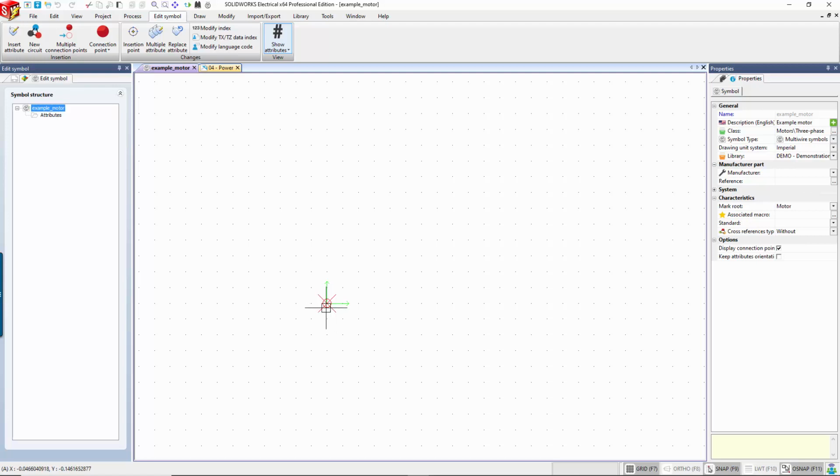The insertion point means that when you drop the symbol on the page, where is your cursor going to be relative to the symbol? Most of the symbols that are already in the library have the insertion point on the first pin of the symbol. So that's usually a good thing to stick with, having the first pin have the insertion point on it, so you know where you're dropping it is usually pretty handy.